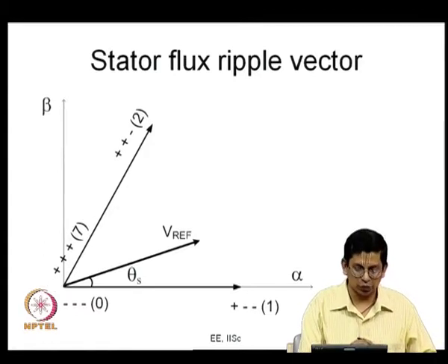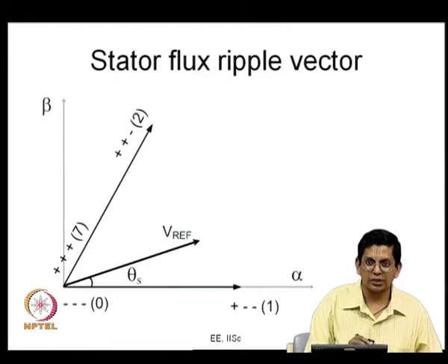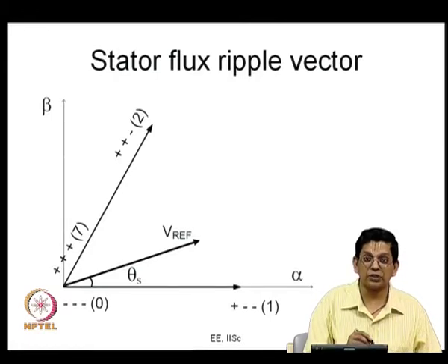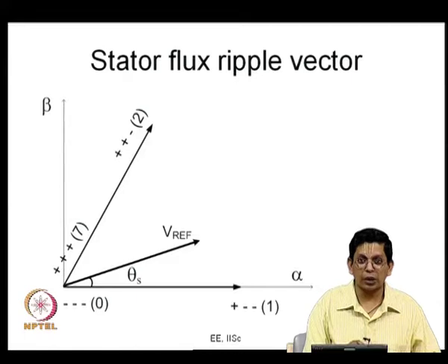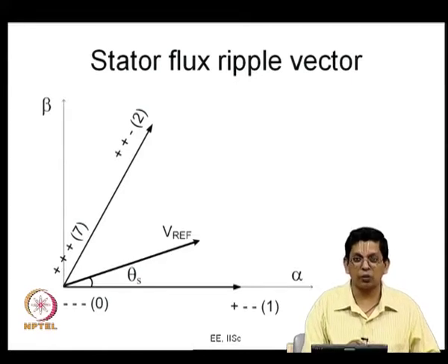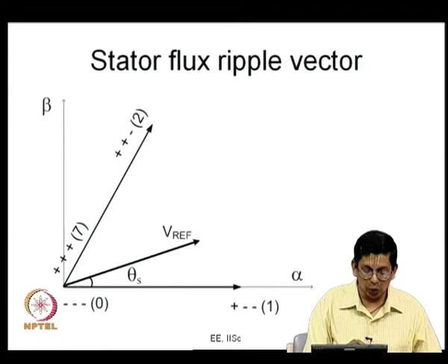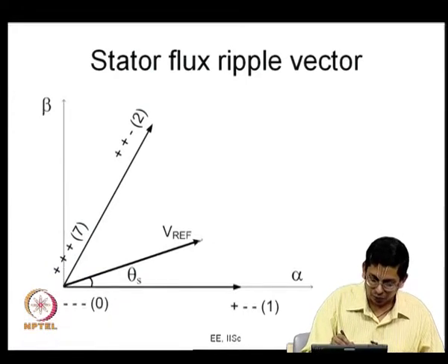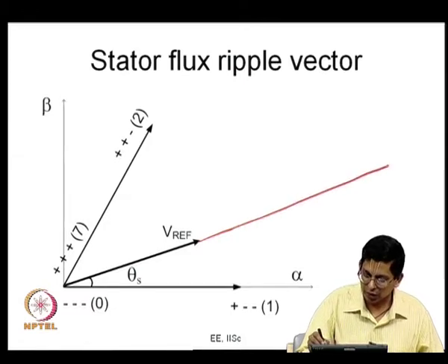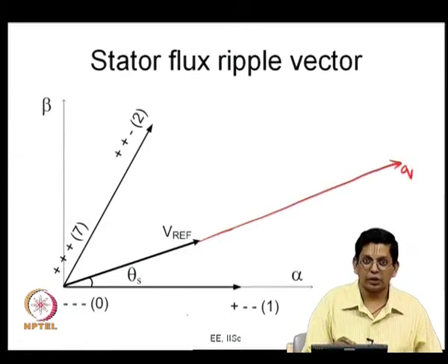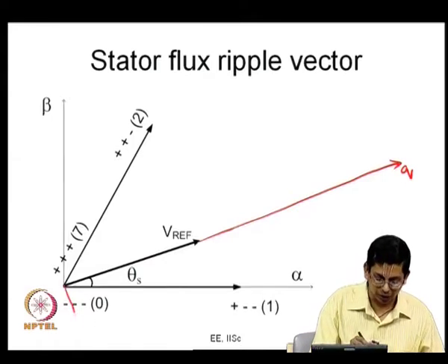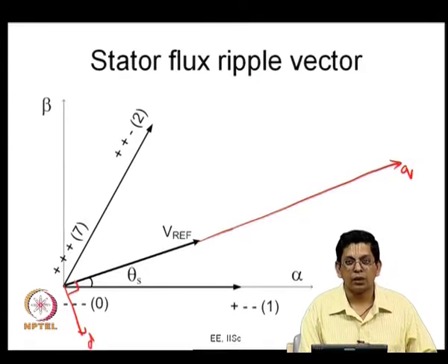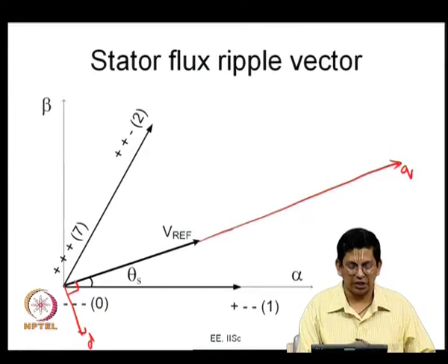So, let us do the job now. Let us do an integration of the error voltage vector. We looked at the error voltage vector when a particular state is applied. Now, we are going to look at the error voltage vector and its integral over a subcycle. Let us start with this. Let me call this the q axis. Ignore drawing inaccuracies. It is just a straight line connected to the reference vector, and this is the d axis, and this angle is 90 degrees.